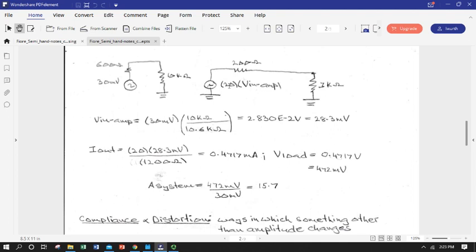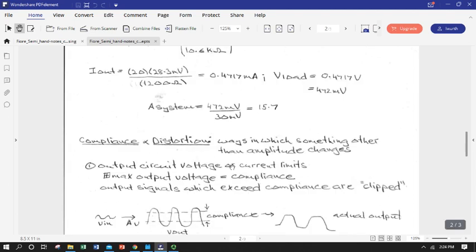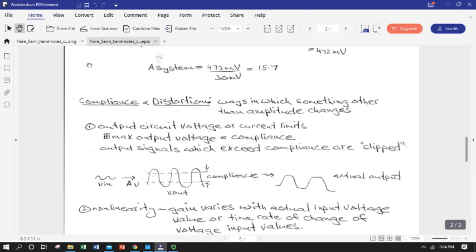So we knocked down 20-25% versus our theoretical gain due to imperfect input and output impedance resulting in loading effects on both ends of the circuit. So this shows you the power of real circuits, loading, and input and output impedance on the performance of a real amplifier. Okay, so there's loading effects affecting our gain.